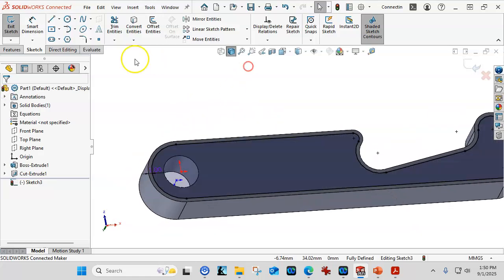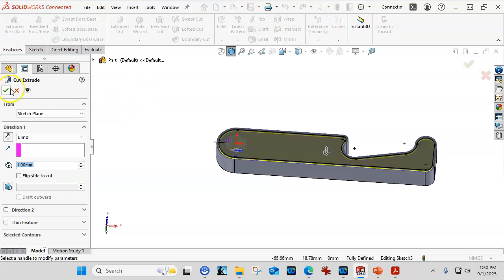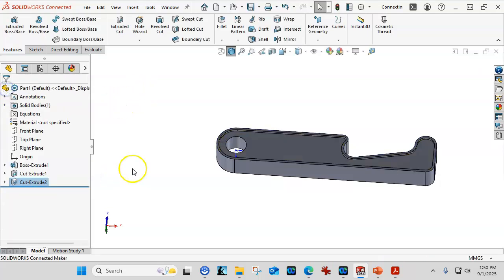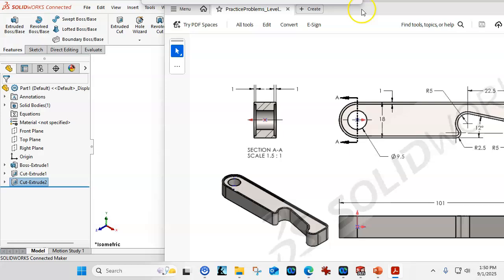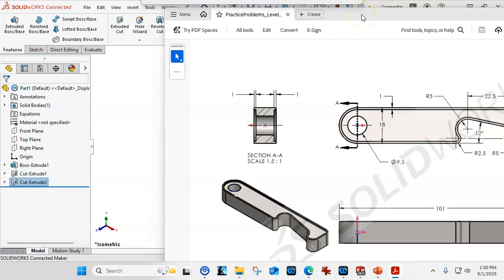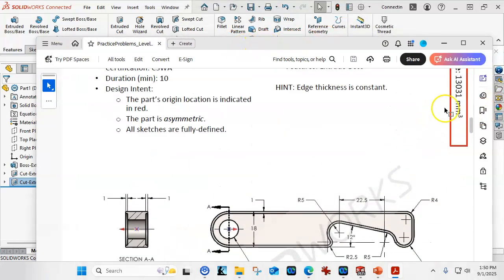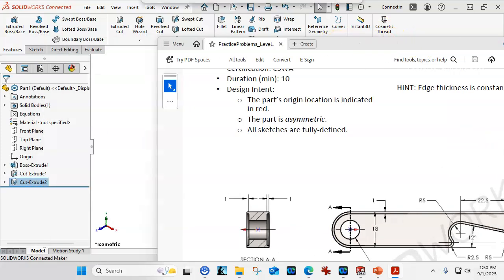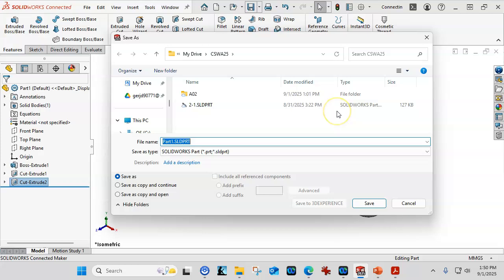We have the offset. We're back into the extrude cut. 1 millimeter depth looks good. We'll go ahead and accept it. Control 7 looks like the picture, so Control 7 is our isometric. It looks like the picture, and we're looking for our value, which is 13,031. So let's see how close I got this time. Let's go ahead and save this.